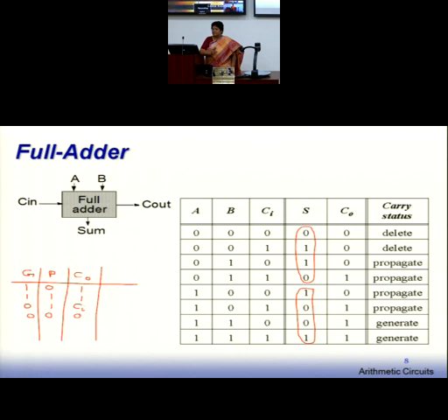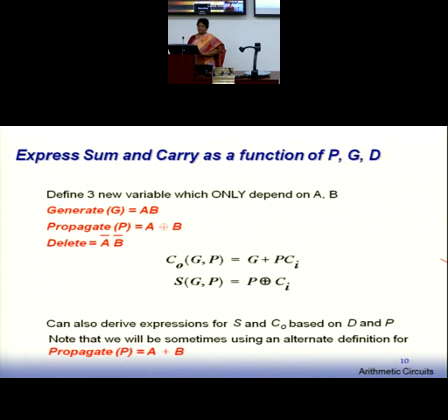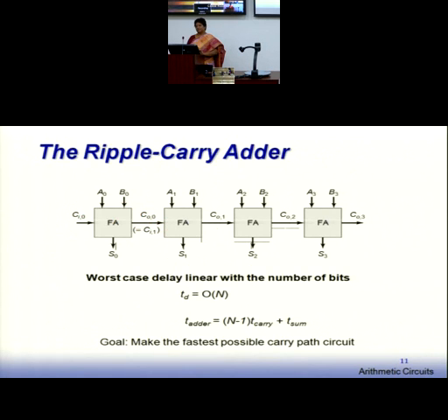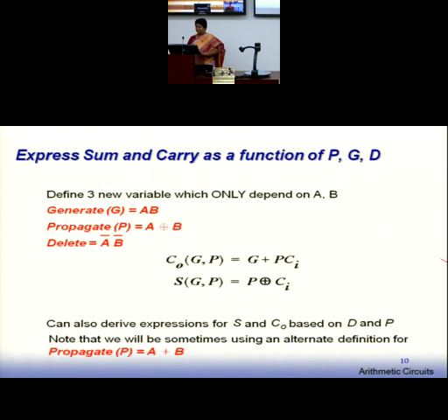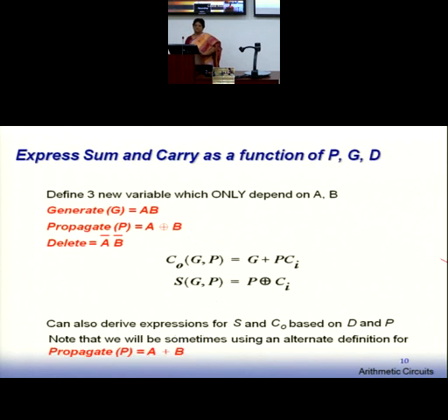You can write those equations, generate, propagate, and sometimes you can also represent in terms of kill if you want. Generally we can write in terms of generate and propagate. So these are the equations that we start with, and we use this equation to get our first architecture, that is a ripple carry adder, where you are using these equations, or you can also use the equations in terms of generate and propagate functions.